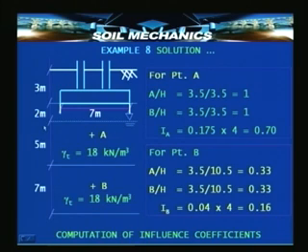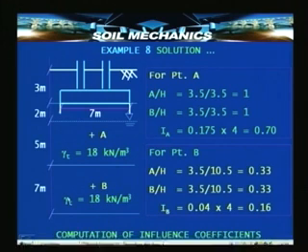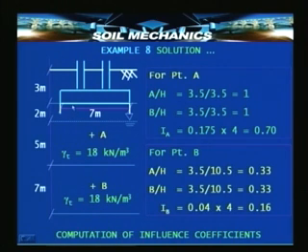Here is the foundation. In our case, it is 7 meters by 7 meters. The layers involved are 3 meters and then 5 meters, 7 meters and so on. If you remember, the foundation is kept at 3 meters depth, and that means there is a 2 meter thin layer just below the foundation, and the water table is at that depth. This is as per the data collected during subsurface investigation. That means below the foundation 2 meters of the soil is dry or maybe capillary saturated, but we shall take it as dry, and below that the soil is saturated.